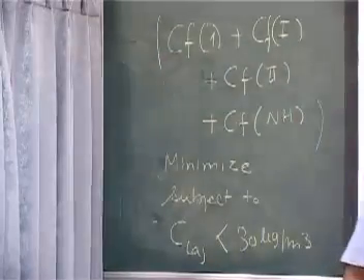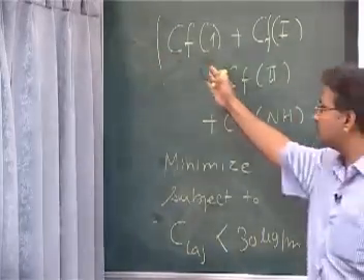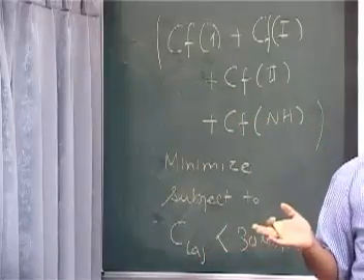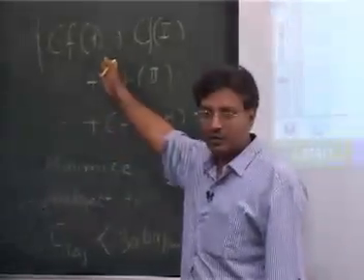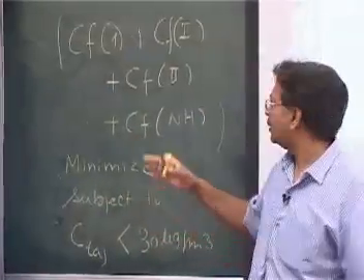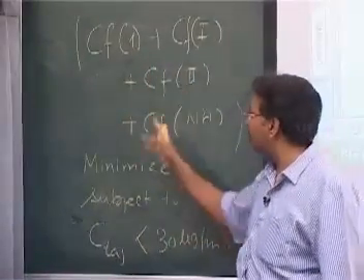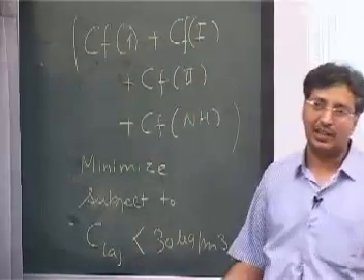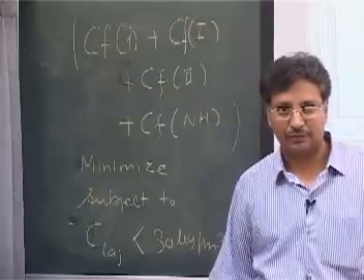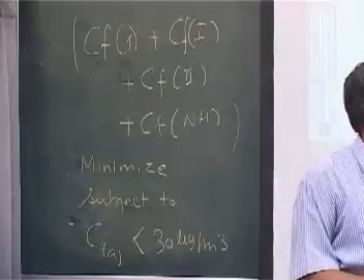That is what we want to do. This also costs money, so after all it is national money, right? And you want to plan something for your area, then you develop the cost function. We are not getting into the details here, but you minimize this cost function, subject to the concentration at Taj Mahal being less than 30 micrograms per cubic meter. This is how we do things.